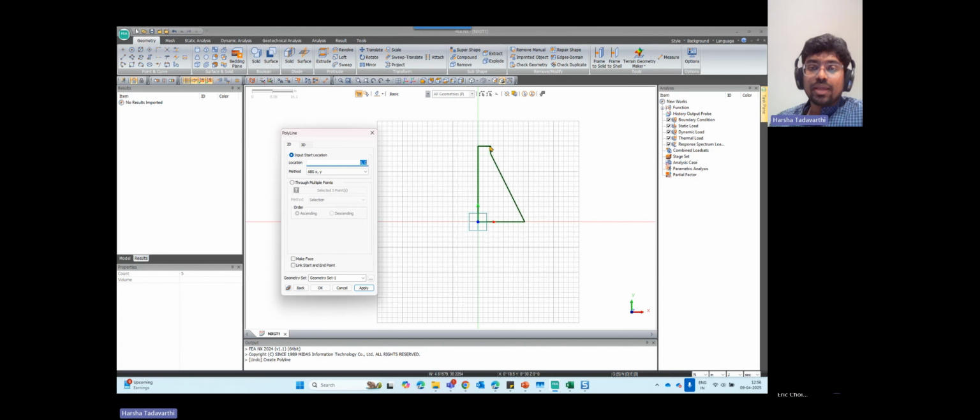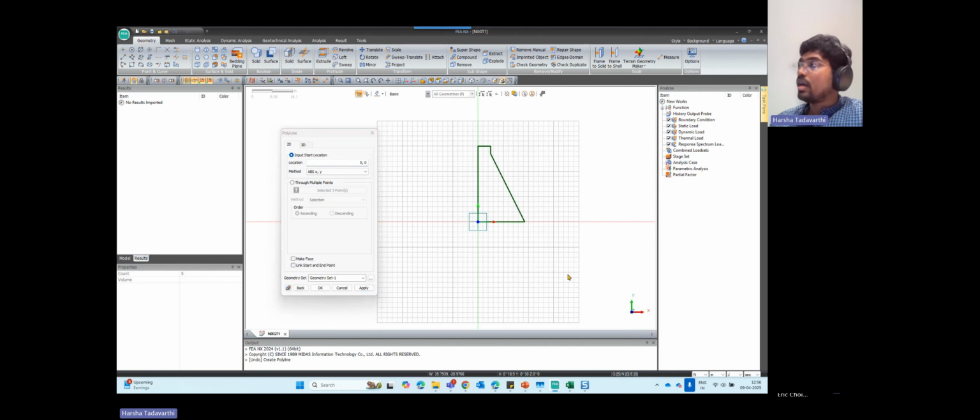And then we inputted 5, 0. And then we inputted 0, -3. And then we inputted 13.5, -27. Then we got the downstream slope. And then we can input the base of the dam by inputting -18.5, 0. So this should be the output that you can expect from your model.